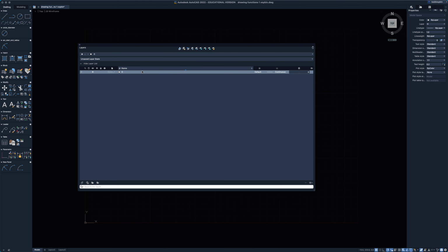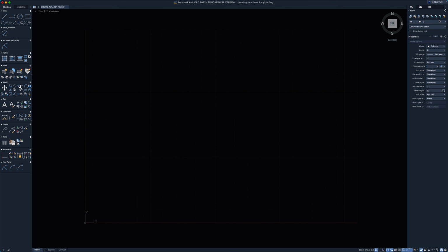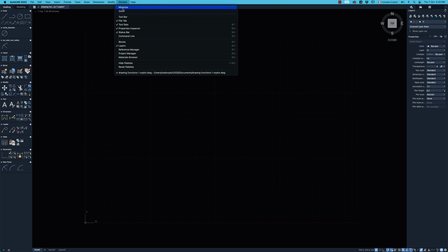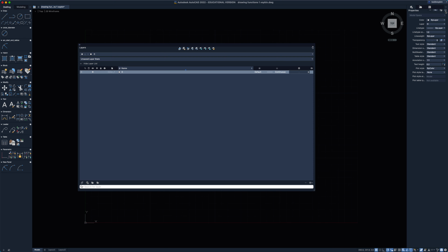So this is the layer window. Remember not to click on that little X. We use the little docking symbol at the right, which puts it back over to the right. And if I want to open that window again, I go to the top right, find the layers window, and click on the little docking symbol. Again, if it's not there, go up to the top into the menu bar, choose window, and make sure that the layers window is selected. Okay, so I'm going to open that up by clicking on the docking symbol, go down to the bottom left corner and turn on the caps lock.